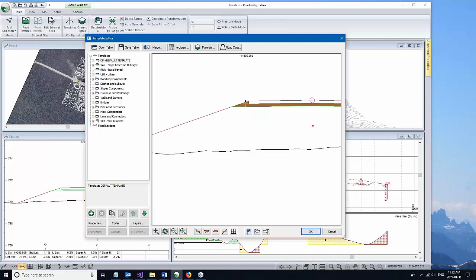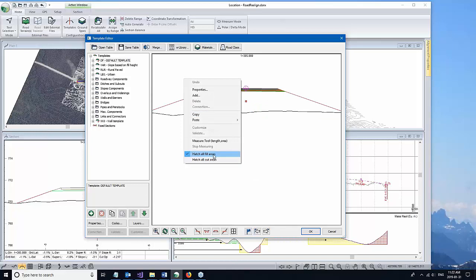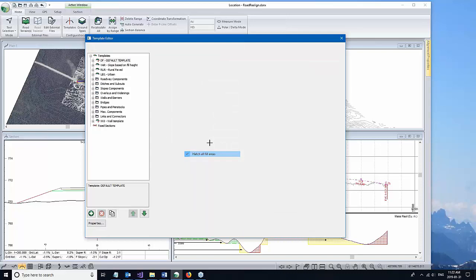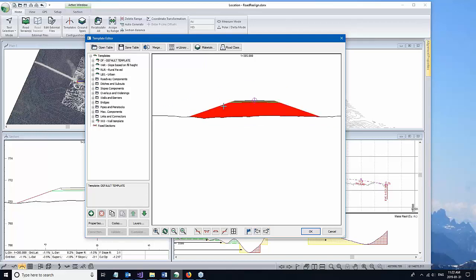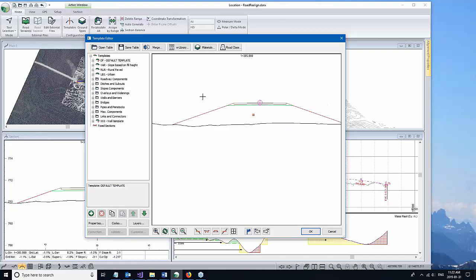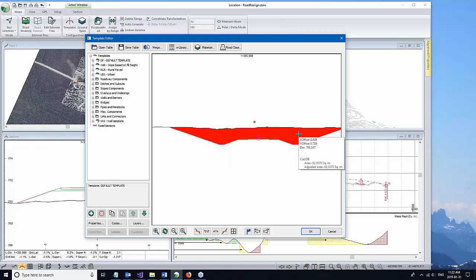And similarly, I can shade the SRF3. I can shade all areas. So now I've got the subgrade material shaded, and it also reports the cross-sectional area of those materials. So it's quite useful for diagnosing what's going on using the shading and the hovering to just see what the materials are. That's fill materials. I can shade cut materials, and then I'll move down into a cut situation. You can see all that's cut material, and yeah, it's a very useful tool to have.